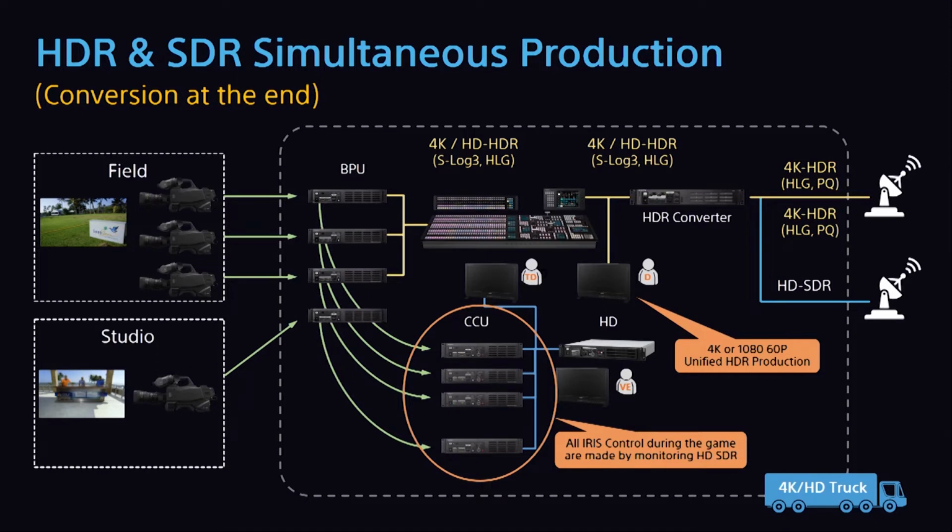Games, sports, live applications, entertainment will follow this workflow. The cameras will be feeding the HDR layer into your live production environment. The CCUs will output the SDR so that the video engineers will shade. And the conversion devices will produce simultaneously the HDR feed and the SDR feed.